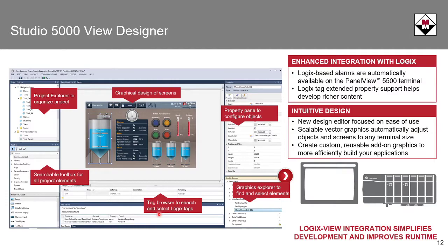The pre-configured banner, alarm, and diagnostic screens reduce your design time since there's no development required to utilize them. Logix-based alarms reduce alarm configuration required in the HMI. The add-on graphics capability allows you to reuse screens and graphics tied to Logix structures. With Logix shared tags and extended tag properties, there's no need to create HMI tags in your HMI project. And scalable vector graphics automatically adjust objects and screens to any terminal size.